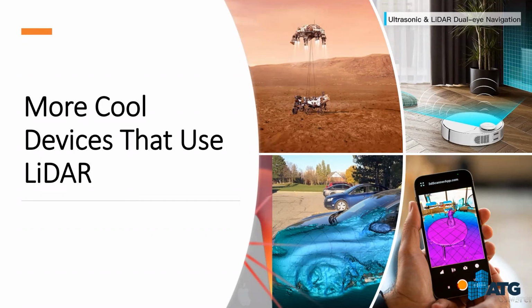I've seen a lot of them, while the concrete is curing, fly the drone at night, or do some scans throughout to make sure that they have everything built correctly, because the last thing you want in any kind of transportation project is ponding within your parking lot or on your streets, because that's how you get potholes. That's how you get a lot of erosion really quickly.